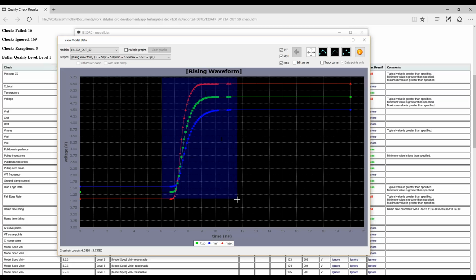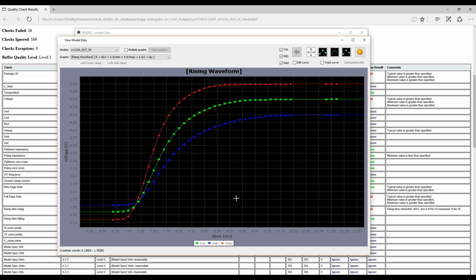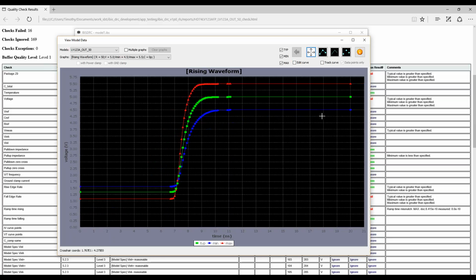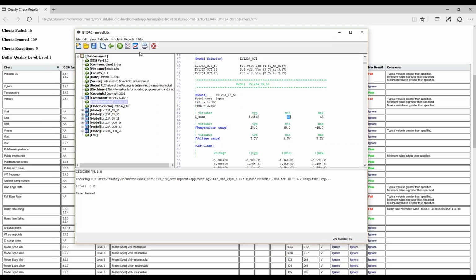And then some of the simulators will have problems with that. So really what you want to do is just take this chunk of data. You could do this within 4 or 5 nanoseconds instead of 20. The rest of that data you don't need. And again, you really need to simulate this with your desired input frequency to make sure that it's going to simulate fine. You won't have an overclocking issue. But that's sort of how you could check the overclocking issue in an output model.